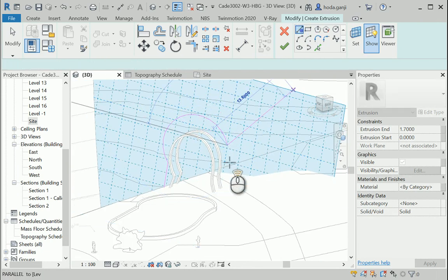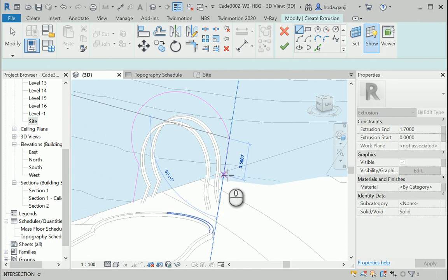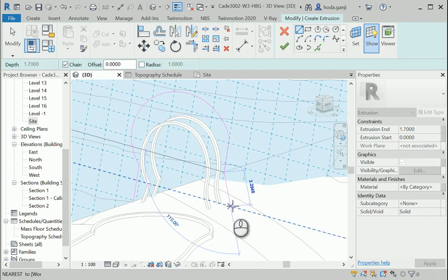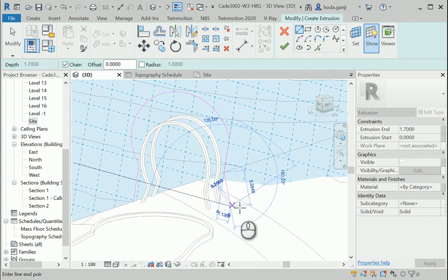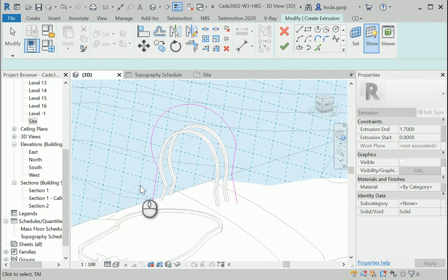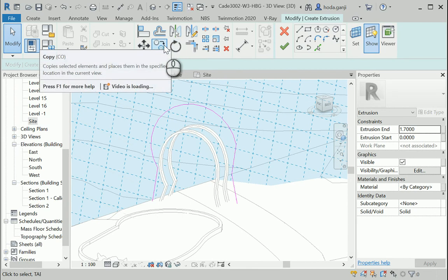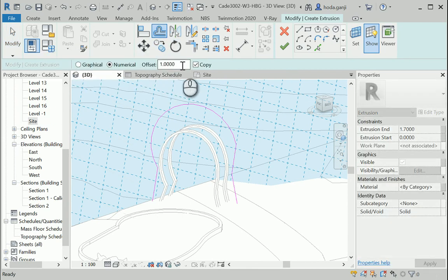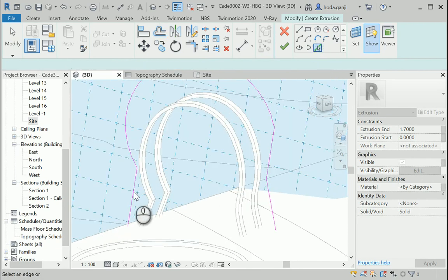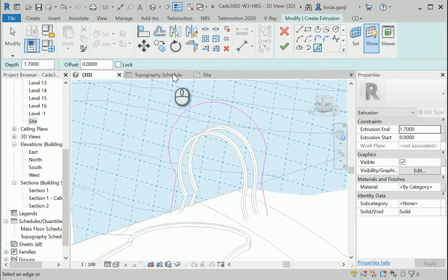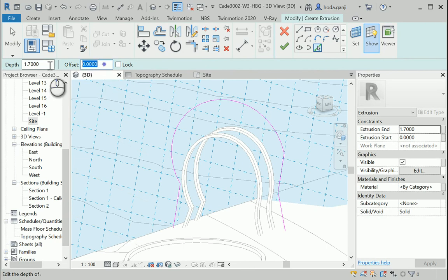You can design any element that you wish, and it can go below the surface of the ground. That's totally fine. Actually, it's better because we somehow need to extend it below the ground to have a little bit of leverage. So how about I use offset? Maybe I can offset this by 20 centimeters. Pick the lines, and point to here again.